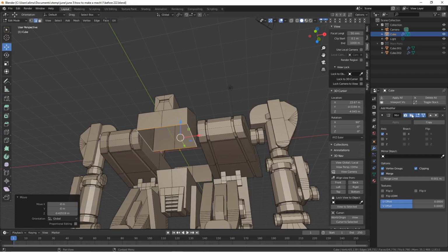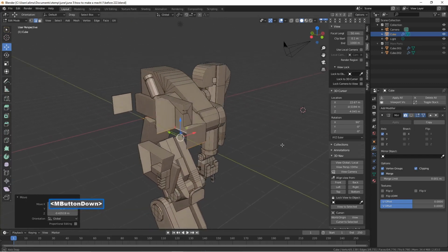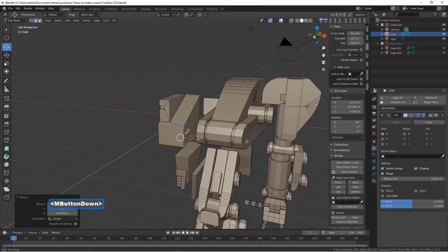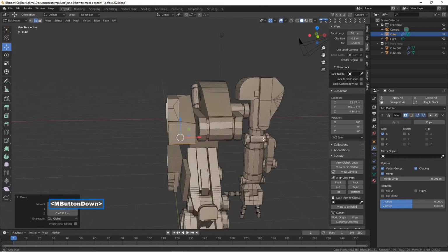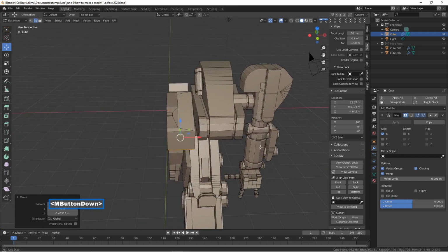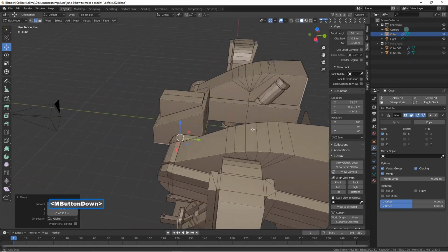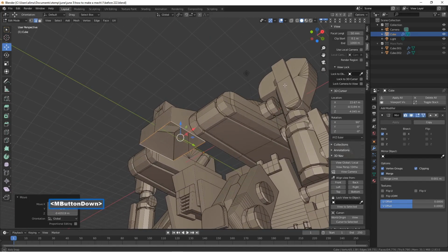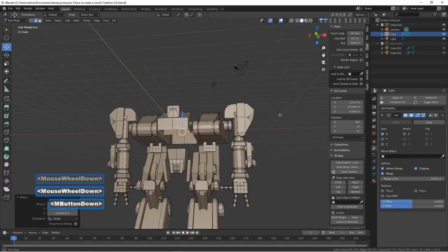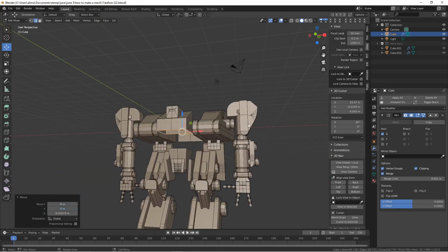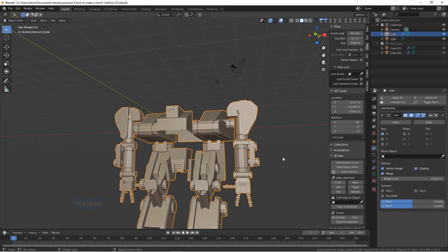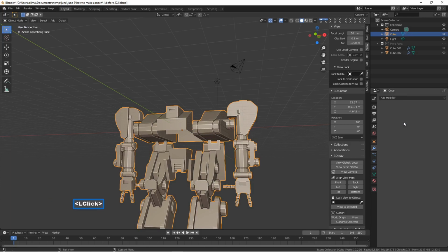Okay, I'm going to go to the mirror modifier. I'm going to select the mirror to temporarily turn that off. Okay, so I'm taking a look. So what I'm going to do is I'm going to left click to deselect, still have an edge selected. We're going to go to the upper left hand corner, go to object select. I'm going to select to apply the mirror modifier.